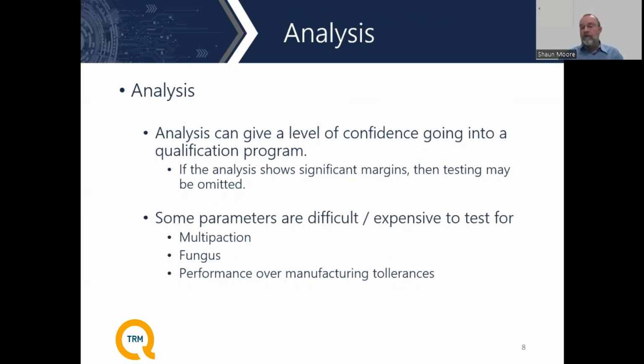It's a very long test to run, and quite frankly, it eats up a lot of schedule to actually run that test. And if there are no known elements in the component that will feed a fungus growth, or that can be a fungus nutrient, quite frankly, there's no sense in running the test. Those are a couple of cases where analysis would be done in lieu of an actual test.